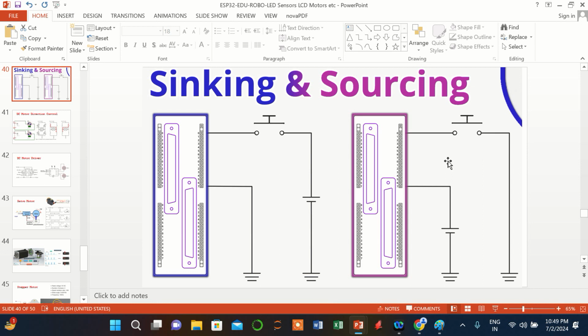However, you can connect the switch, which is an input device like a sensor. A switch is also a sensor which is detecting whether it is open or closed, right? Like in doors, we use it generally in refrigerators, or maybe CD players, music players, or door opening and closing in public places, and so on, or even printers or two-wheelers, four-wheelers. At several places, we use these switches to detect whether the door is open or closed. Even in robotics, like a touch sensor, we use it for any obstacle. If the robot hits, then it will come to know. It is open or closed. The switch is pressed or released.